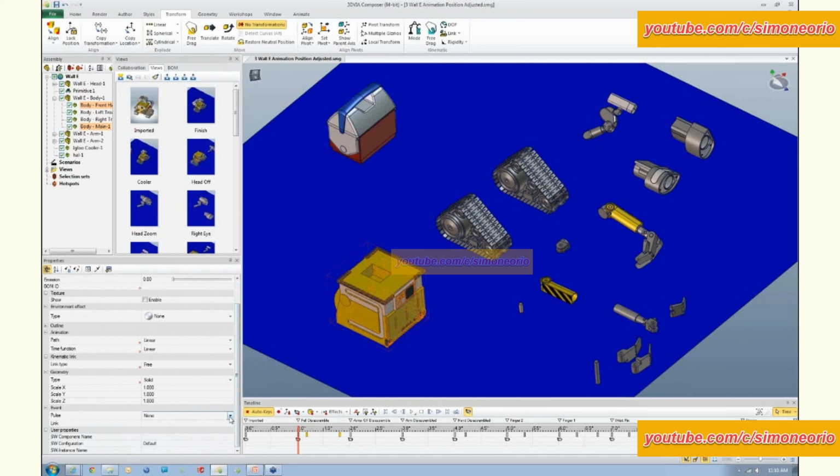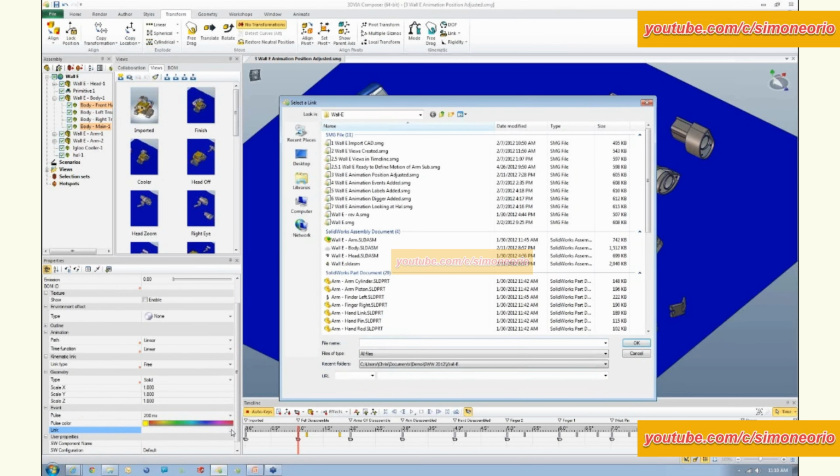Down in the lower left-hand corner is where we find that in the property manager, and it offers us 200, 400, 800 millisecond pulses, and we can come in here and make it a different color blink if we want. And then in the link row, all the way to the right hand side, there's 3 little buttons, maybe hard to see on the screen, but this is what we're going to tell it to do.